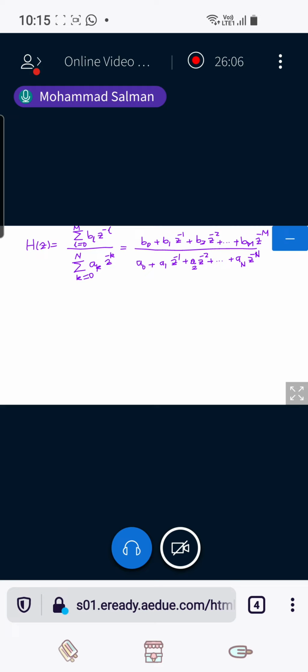Now, what we want again is h of n. I have h of z. If I have h of z, how to find h of n? I go to the tables. A reminder to everyone. I go to the tables. I look in the tables. Do I have the same function in the table? Yes. Done. No. Then I look. Do I have the same denominator in the table? Yes. Done. No. In that case, most probably we need partial fractions, right? We need partial fractions.